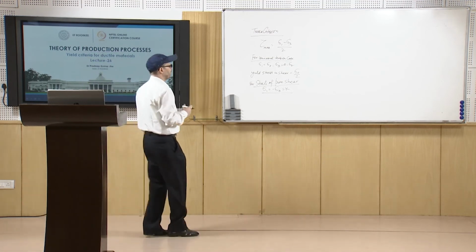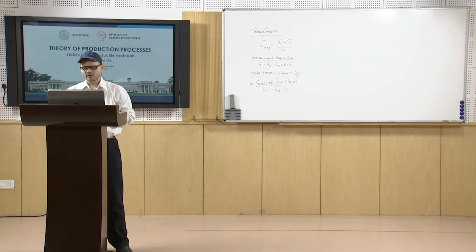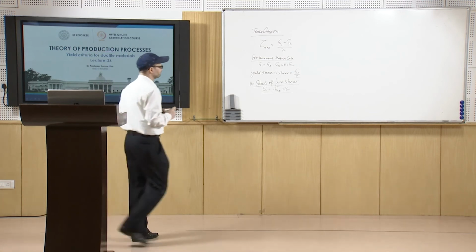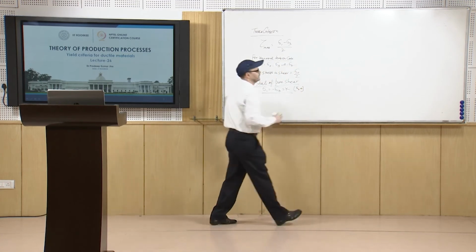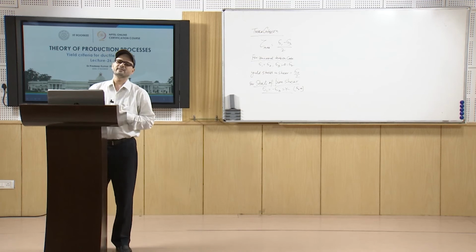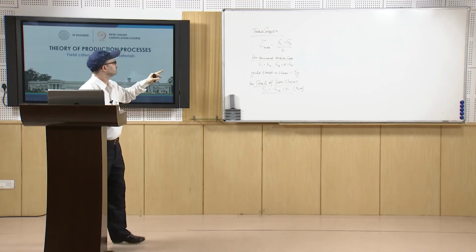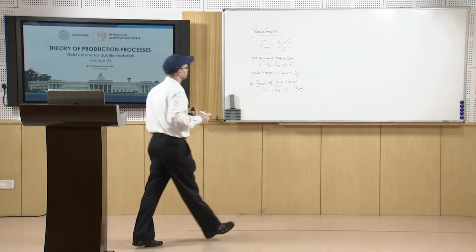So, that is why, once you have the state of pure shear, you have sigma 2 as 0 in the case of plane stress condition. Once you have that case, sigma 1 minus sigma 3 will be 2k, and that is equal to sigma naught.